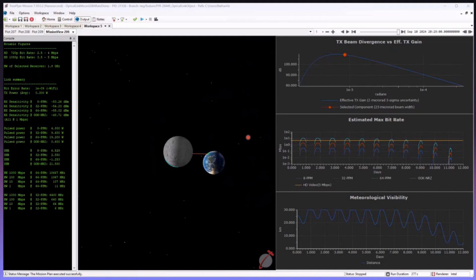Because that feeds into the middle plot I'm going to talk about here, which is an estimation of the maximum bit rate you could get from various modulations that you could select. We talked about PPM here, and these kind of dominate the spot. I didn't talk about it in detail, but we showed a 4 PPM example in the modulation slide. So that was 4 subdivisions, but you can go up into many more different subdivisions. Here we've gone all the way up to 64 PPM, so you'd have 64 subdivisions. It's probably going to get harder to design, because you're going to have a tighter timing tolerance. So that's an interesting parameter you want to look at.